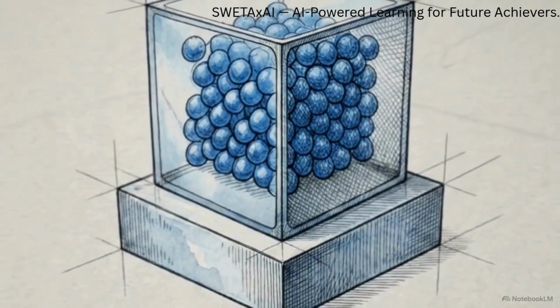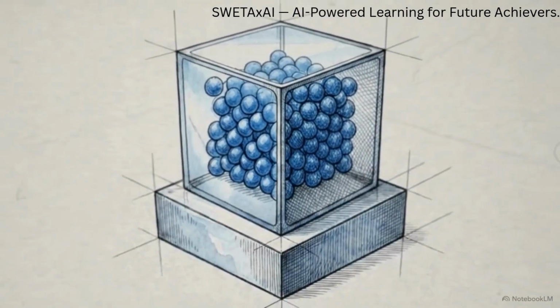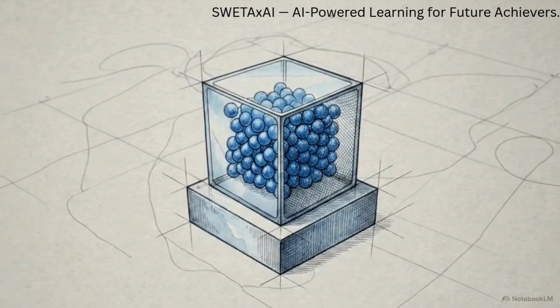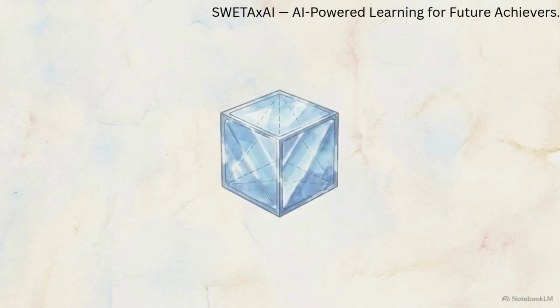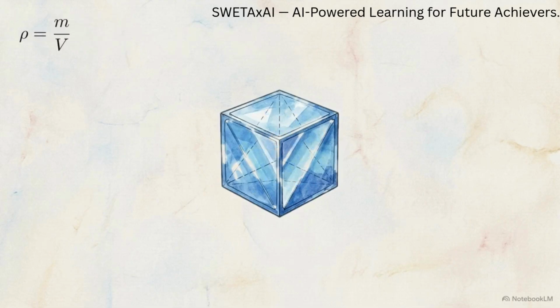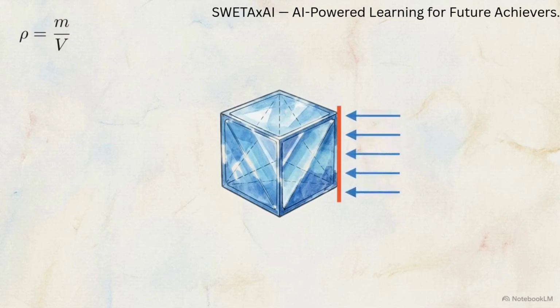To solve problems in fluid mechanics, we have to abandon the particle-level view. We shift our focus to a continuous volume-based system. Instead of measuring absolute mass, we measure mass per unit volume. We define density, represented by ρ, as the mass equivalent for fluids. Similarly, we replace isolated forces with pressure. We calculate a continuous normal force over a boundary area to find the pressure.